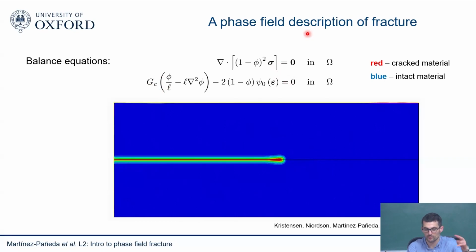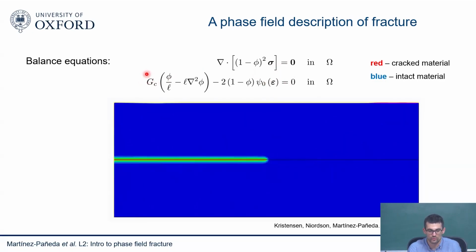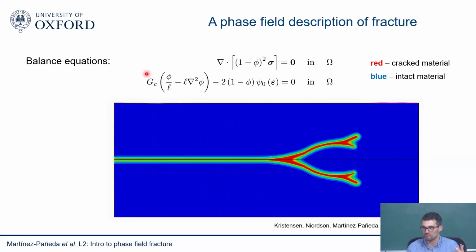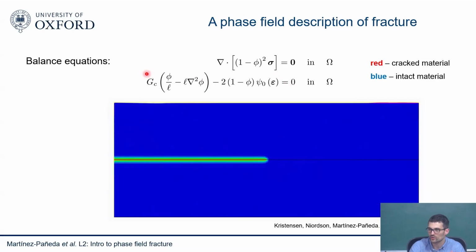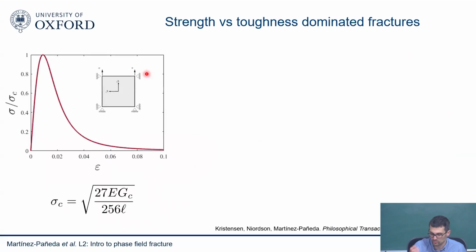So that's the benefit. You're solving independently, so that has some computational advantages. And the other one is that you only rely on one parameter that has a clear physical meaning, that you know from a fracture test, and you connect damage and fracture mechanics very well. I think those are the key advantages, versus non-local continuum damage mechanics.